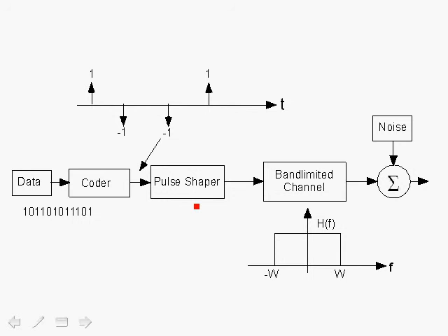This block diagram shows the baseband digital communication system, the transmitter. In this case, data is being generated, ones and zeros. For example, random. The data could go through a scrambler and be scrambled in order to randomize it. It's always a good thing to randomize the data, as we'll show later, in particular in terms of timing recovery performance. In the meantime, we're generating ones and zeros.